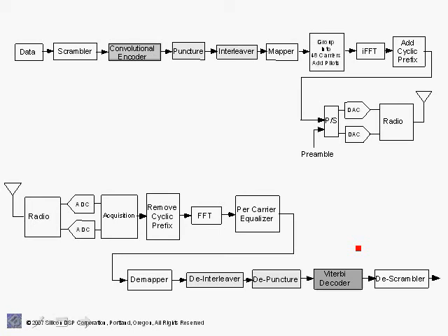Typically in a wireless digital communication link in which you have fading multipath channels where you can encounter deep fades and a carrier, for example, could be wiped out, it is not sufficient to add a forward error correcting code. The problem occurs as follows. If during the transmission a particular carrier is wiped out or happens to fall on a deep fade, then all the encoded bits associated with that carrier are in error, and you have what you call a bursty error. Many forward error correcting codes are not good at correcting bursty errors. That is, errors that are associated with bits that are adjacent with each other.